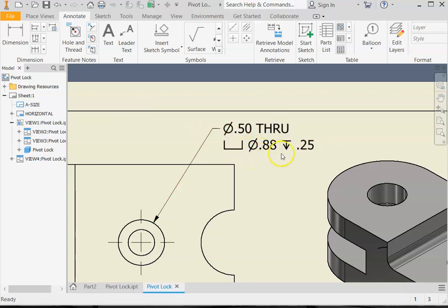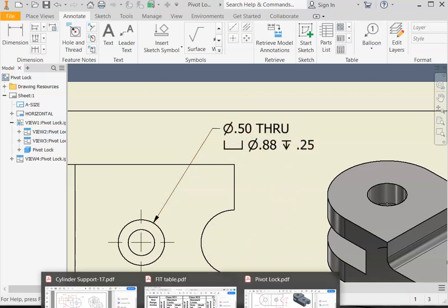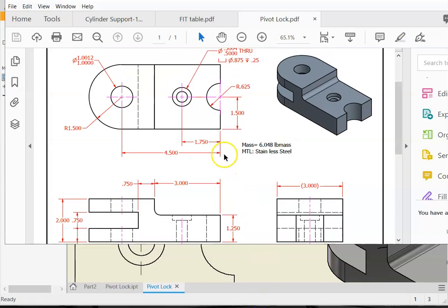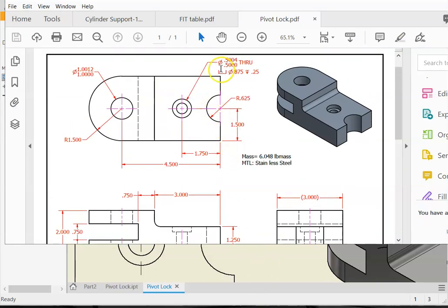Now, we have to make some changes to that because we want to display the tolerancing. If you refer to your handout sheet, I have given you the solution for that. So it's 0.5004, 0.5, and then after that 2 zeros and then 4. And remember where this 4 comes from: that table, which adds to the positive value. And the negative value, the lower portion of this tolerancing, is 0.5, nothing changed on that one.